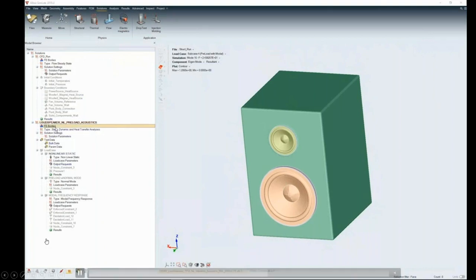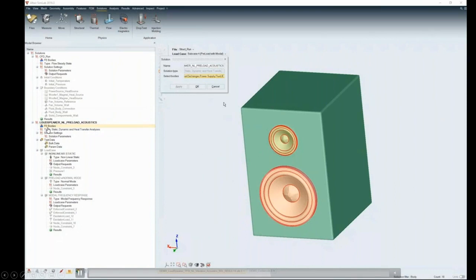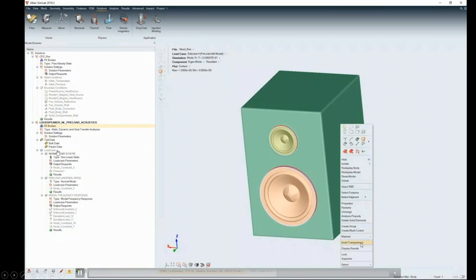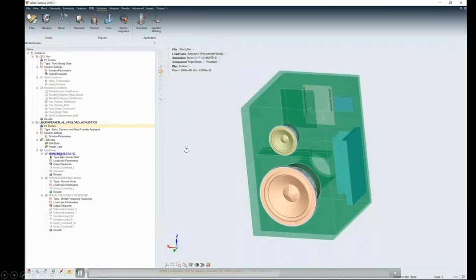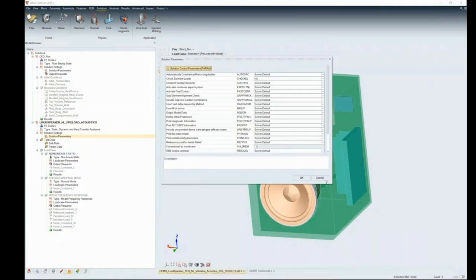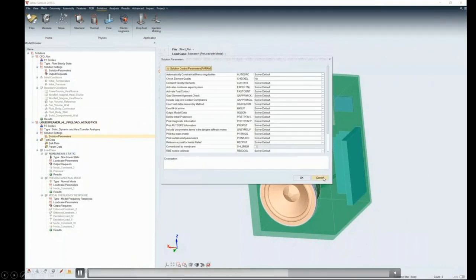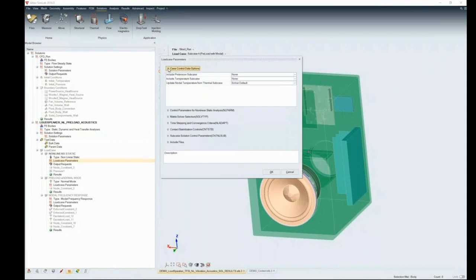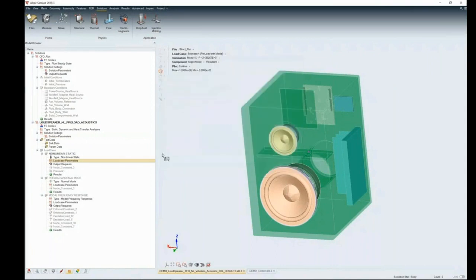Now, in the solution browser, you also have the FE bodies, which are part of the whole ecosystem of the structures. And also you have certain global settings, and then you have certain local settings for each of these analysis. In terms of the structure, these are the global parameters which are set for all types of analysis which are included in OptiStruct. So this is the nonlinear, the acoustics, and the normal mode analysis, where I'm saying this is a single model, what we are working with in OptiStruct, a single model multi-attribute. I also have output control requests, and I also have constraints and so on.